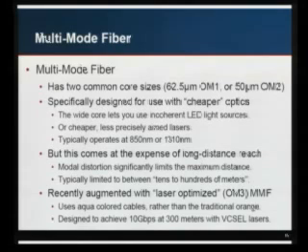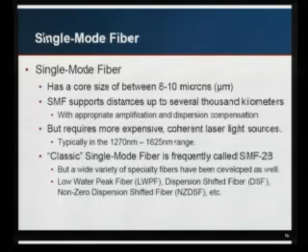There's also a recently introduced standard called OM3, which, if you see it in data centers, has aqua colored cables instead of orange. And basically it's laser optimized. It's designed to work with the new 10 gig lasers and go up to 300 meters and do much better than the older standards. Single mode fiber, by comparison, has a much smaller core.